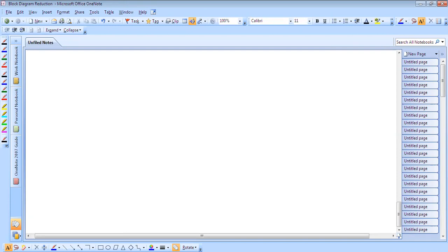It is important that blocks can be connected in series or in parallel. If the output of one block is not affected by the following block, and there is no loading effect between the components, it is necessary to combine these components into a single block. Any number of cascaded blocks representing non-loading components can be replaced by a single block. A complicated block diagram involving many feedback loops can be simplified step by step using the rules of block diagram algebra.